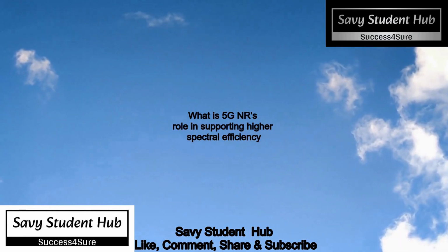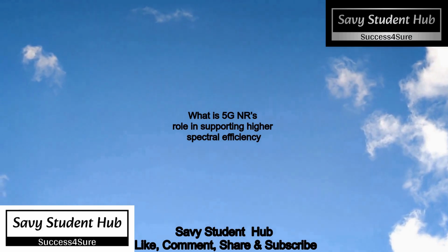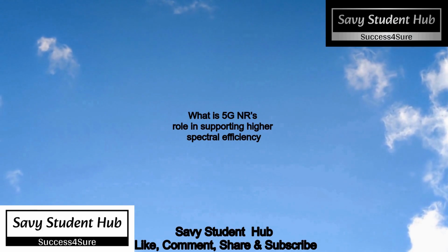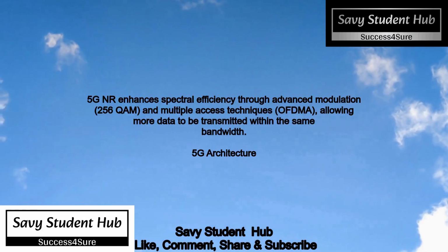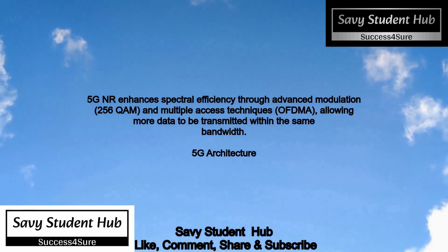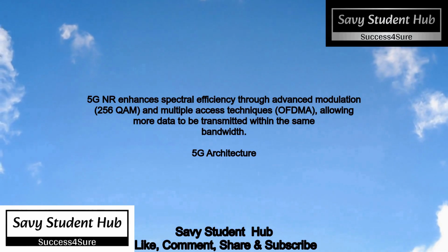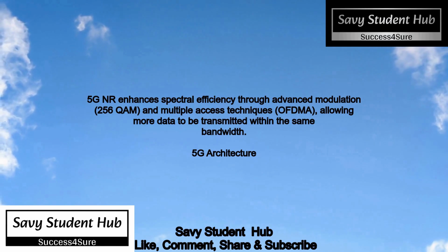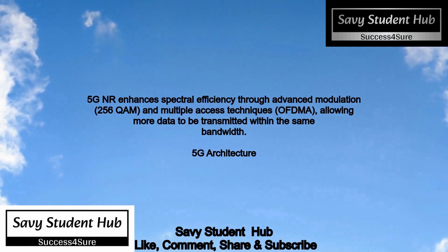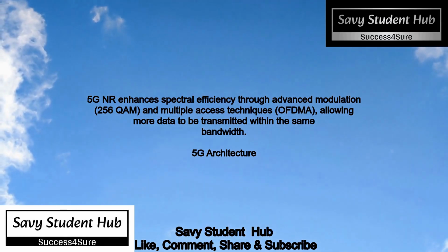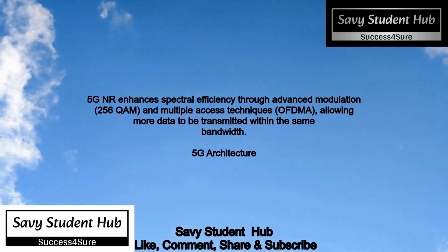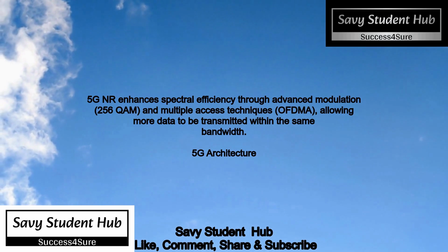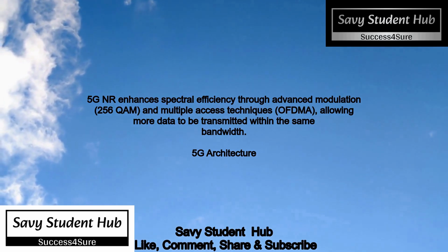What is 5G NR's role in supporting higher spectral efficiency? 5G NR enhances spectral efficiency through advanced modulation, 256 QAM, and multiple access techniques, OFDMA, allowing more data to be transmitted within the same bandwidth.